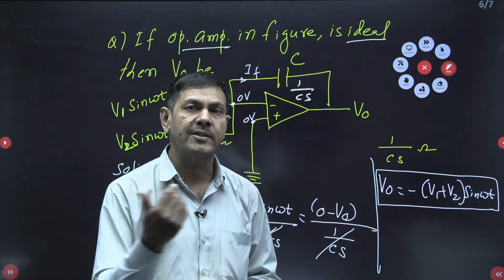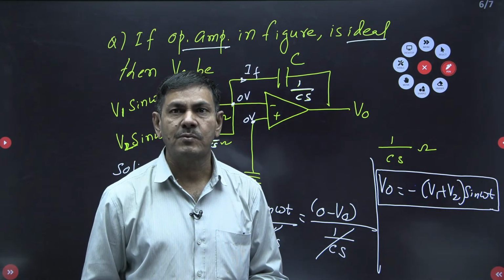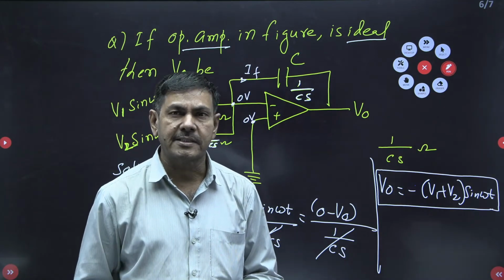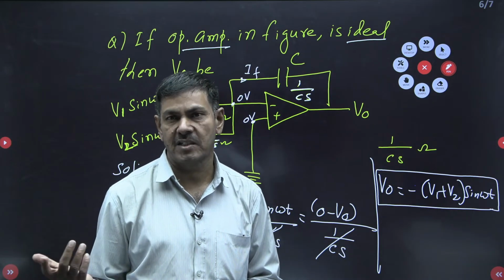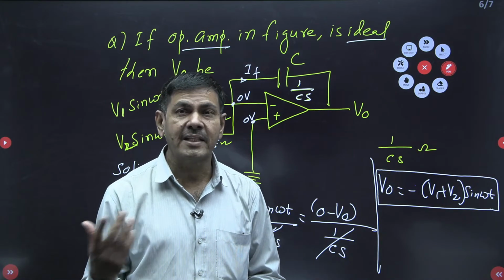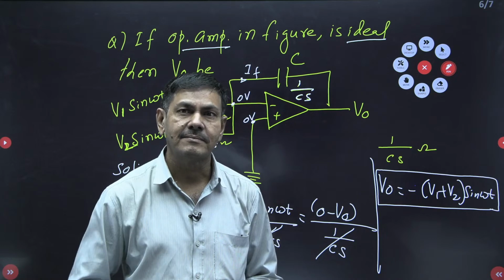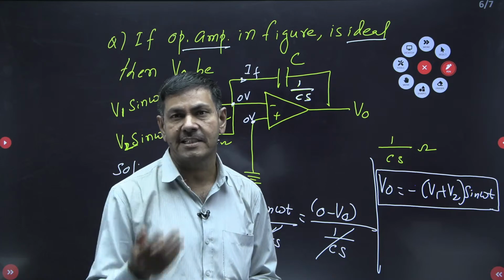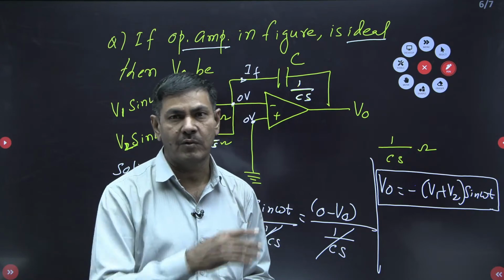Even for the kilohertz you can use this Colpitts and also Hartley oscillators. But if you want to get the frequency in gigahertz, in that case they are going to use the crystal oscillators only. Only crystal oscillators to generate gigahertz. More than gigahertz is not the analog circuits. You need to go to the microwave only. More than that frequency won't come under this oscillators level. Up to gigahertz by using the crystal, that range only we get in the analog.